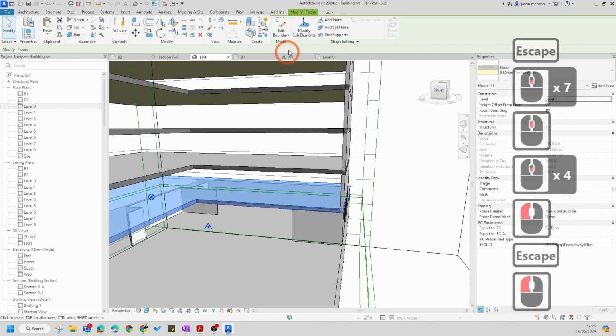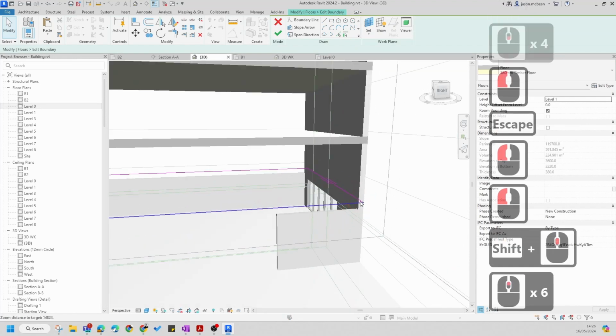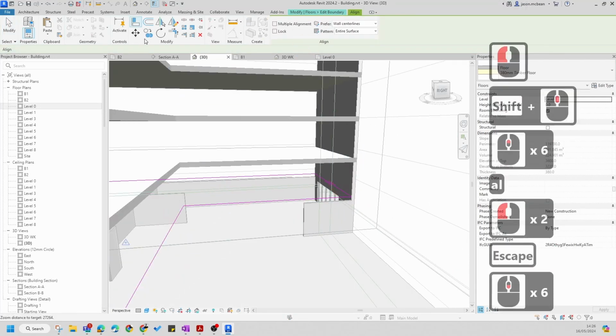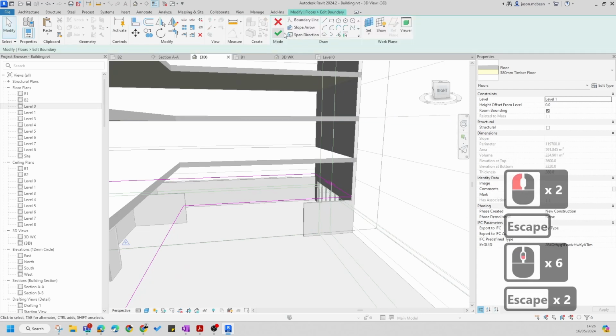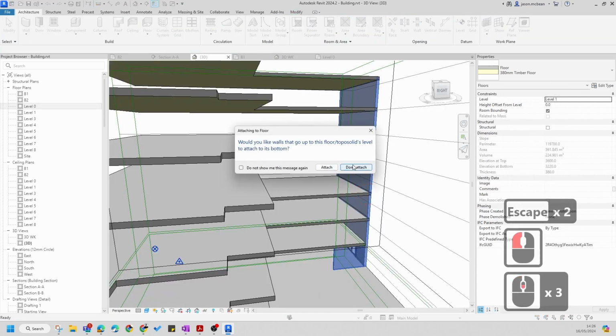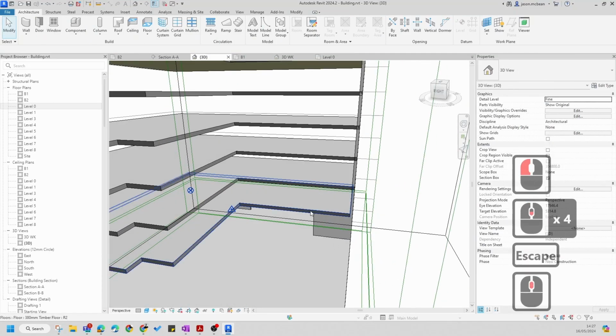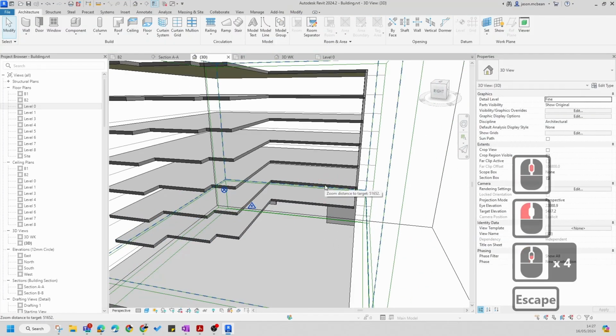And this is a neat trick, so you can go and edit in 3D view, align. So now they've got a wall to work with. I can pick this face and align that. Okay, and then finish the command. Don't attach. Generally don't try and attach the walls. I'll explain why later on, but now you can see the rest of these walls.